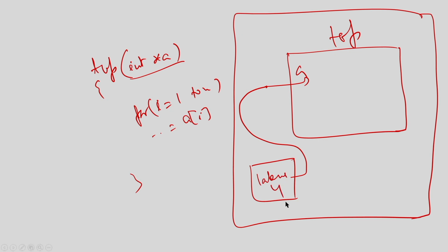That means every 4th cycle it is actually generating valid data, right. Once it is generating valid data, it has to be told that. So, this is A valid, right. That means whenever A valid is equal to 1, only then whatever data is here is going to be accessed here. So, this is a wire connection, but with handshaking happening, right.